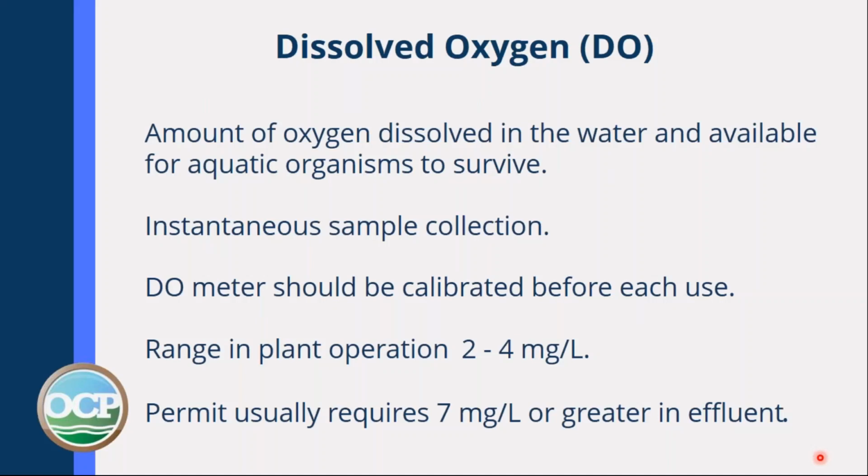We're going to talk now about other parameters. Dissolved oxygen. This is going to be an instantaneous sample, and you're going to read it straight away. It's a grab sample. The meter that you're going to use should be calibrated certainly daily or before each use.